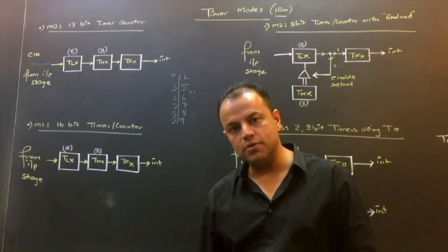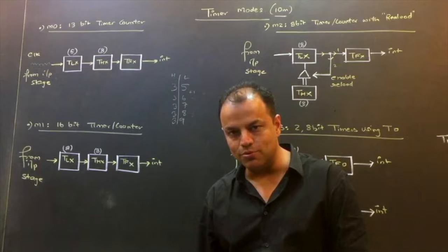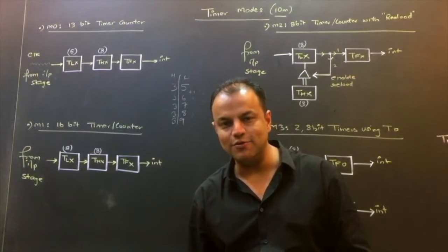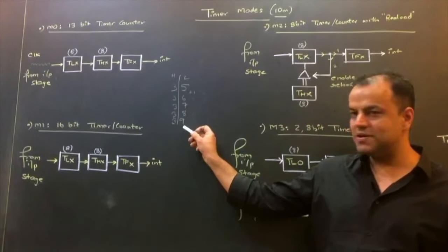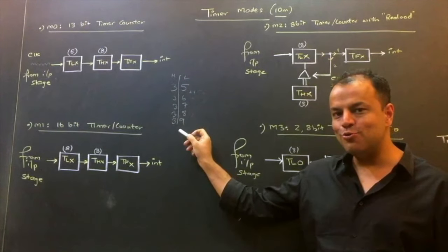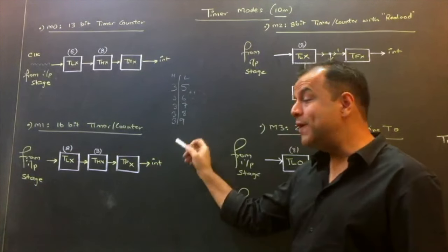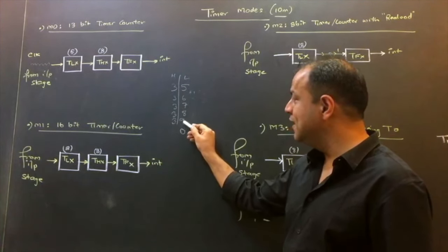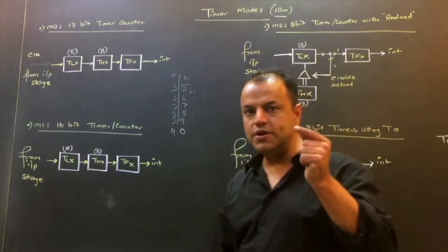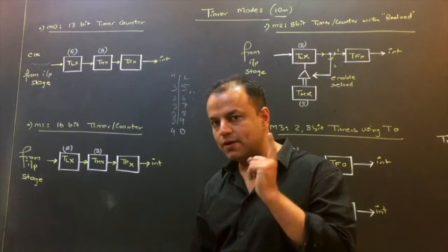You always add 1 to the lower. Come on, you don't add 1 to both, you don't add 1 to the higher. Since childhood you've been doing addition. Addition plus 1 can only happen over here. You only increment the lower. When the lower overflows, it increments the higher. You did not add 1 to both. You added 1 only to the lower.